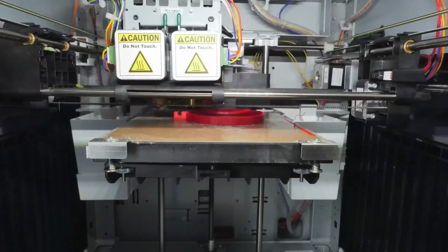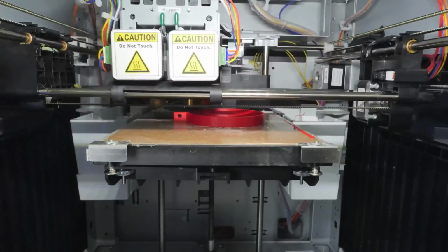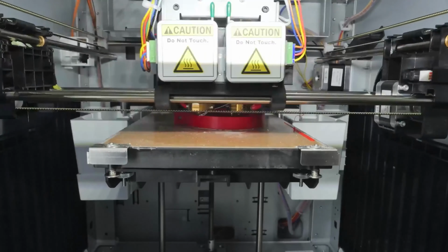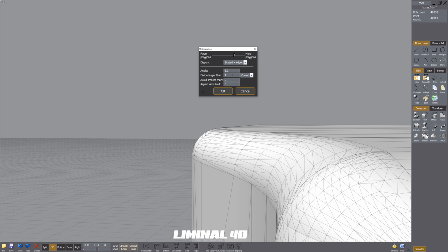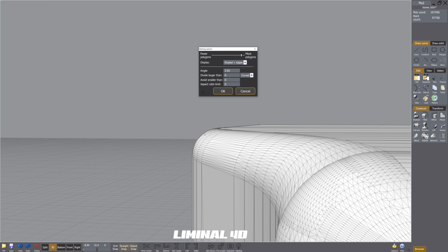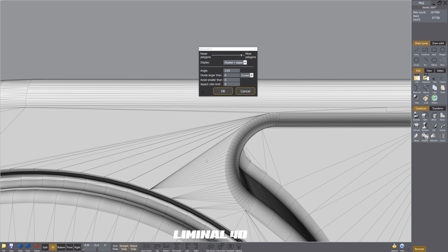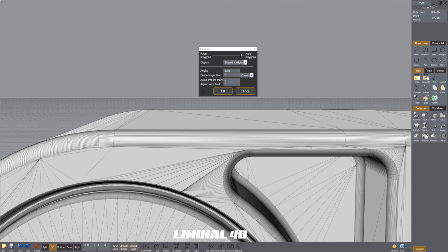If this is a larger part or you have a very high detailed printer, then these settings might not work for you, or you've got more resolution possible there. In which case, if you want, you can reset all these to 0, increase the polygon count, and you're going to increase your resolution. I've got a personal preference. I don't like to see these tiny slivers of polygons like you see in here. I like to avoid those.